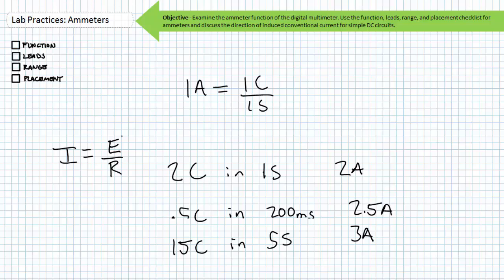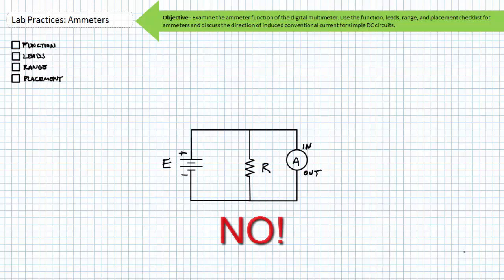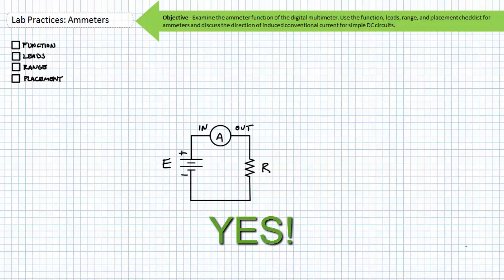of basic electrical phenomenon. The difficulty in obtaining valid current measurements stems from the conceptual differences between it and our previously discussed properties of voltage and resistance. Recall, voltage is a two-point measurement, measured across something, where one point is measured with reference to another. Similarly, resistance is a two-point measurement between the terminals of interest. Current is something totally different and cannot, nay must not be measured across something, but rather through something.